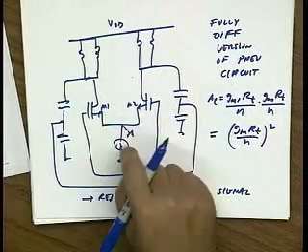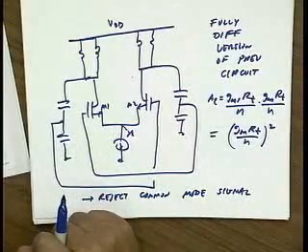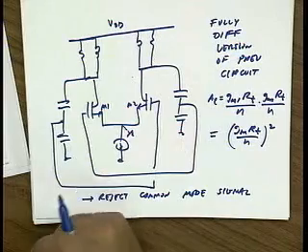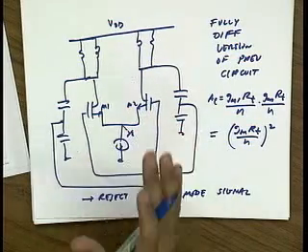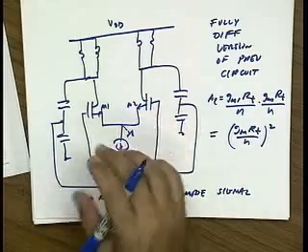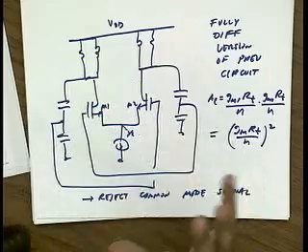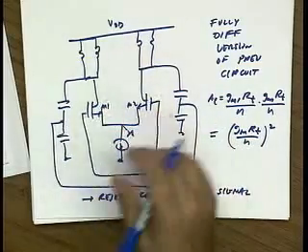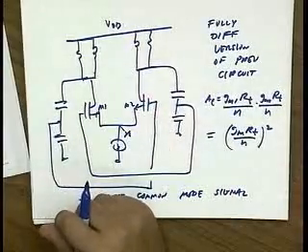We won't talk about it in this class, but this is a nonlinear system, and there's a concept called injection locking. You may have heard about it. It's also called mode locking. The idea is that if another signal comes in that's close to the frequency of this guy, and crudely speaking there's more energy in that signal than there is noise in this circuit, the circuit will lock to that incoming signal.